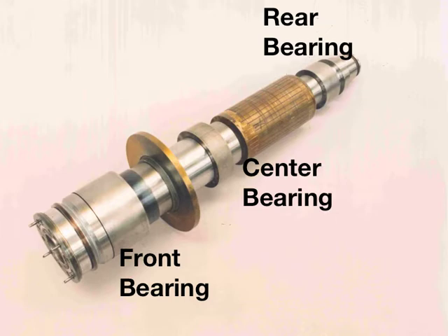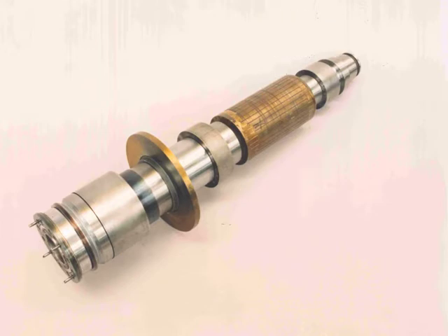We're interested in the transfer functions between these locations and various locations along the shaft. And depending upon what input and output locations we have for the input forces and the output displacements, we'll get different transfer functions. And these transfer functions will have different zeros. The poles will always be the same, although sometimes a mode may be unobservable, like we saw in the tilting beam problem.